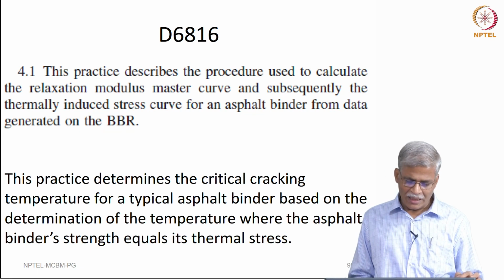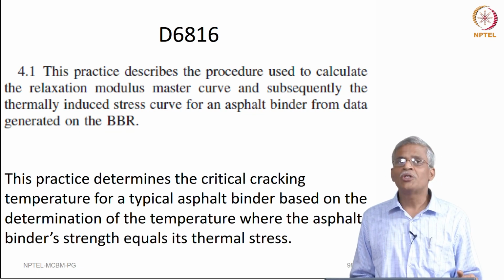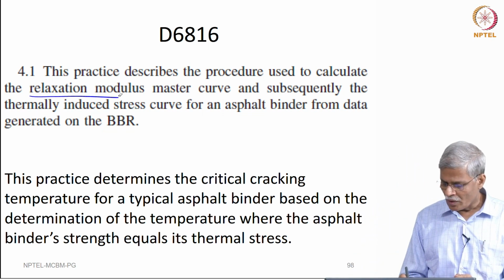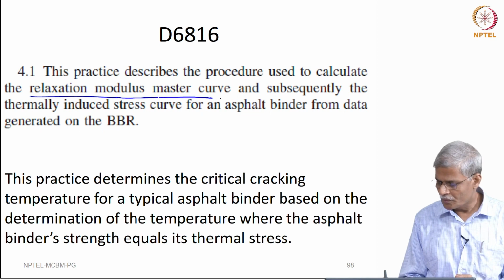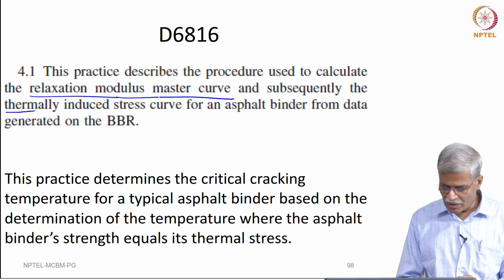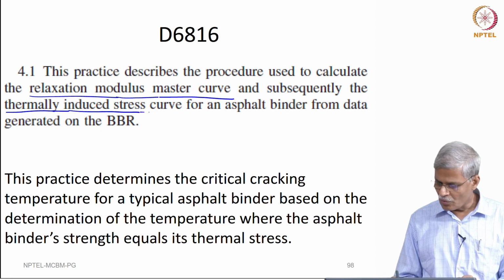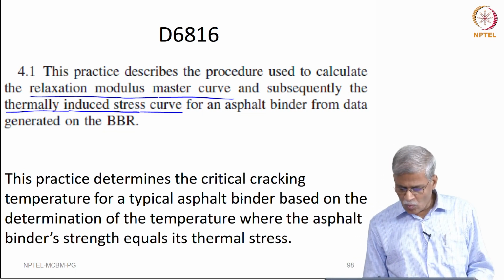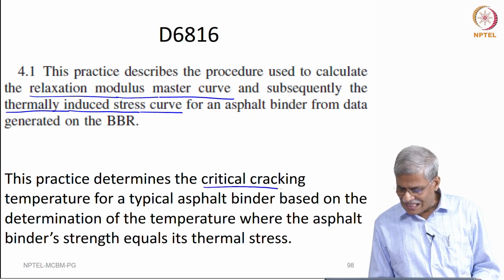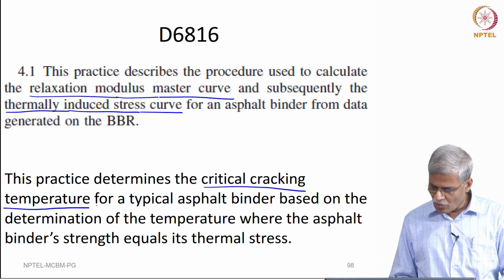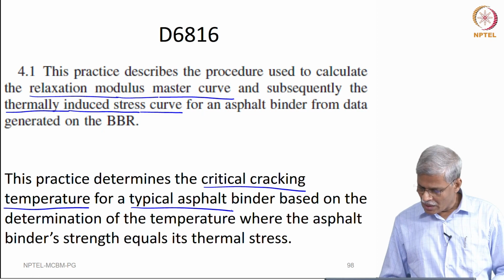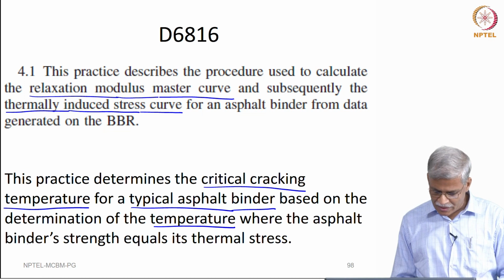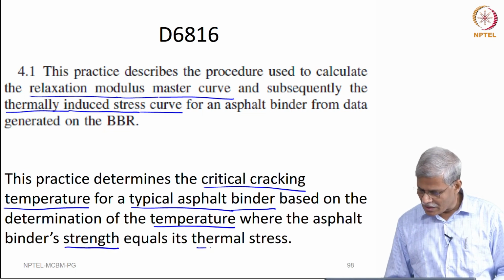It says basically that the practice describes the procedure used to calculate the relaxation modulus master curve and subsequently the thermally induced stress curve for an asphalt binder from the data that is generated from the BBR. So, what you are going to do is you will find out the critical cracking temperature for a typical asphalt binder based on the determination of the temperature where the asphalt binder's strength equals its thermal stress.